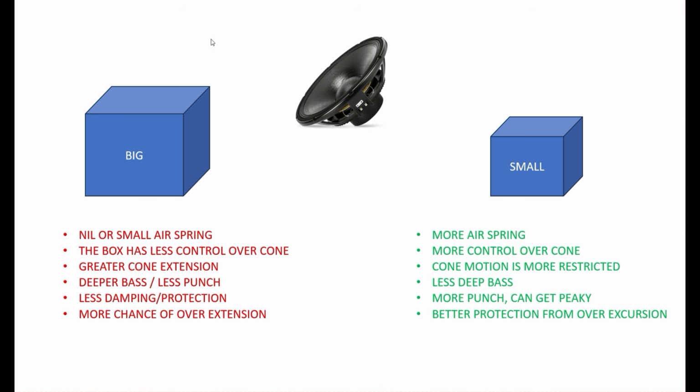You get greater excursion, which means deeper bass and less punch. You'll have more chance of over excursion, and all of the usual stuff that happens when you've got less stiffness in the suspension, because effectively we're reducing the impact of that air spring. And I'm talking about all things being equal here. When you're just comparing a speaker in free air versus a speaker in a big box, not much will change because the air spring is greatly reduced.